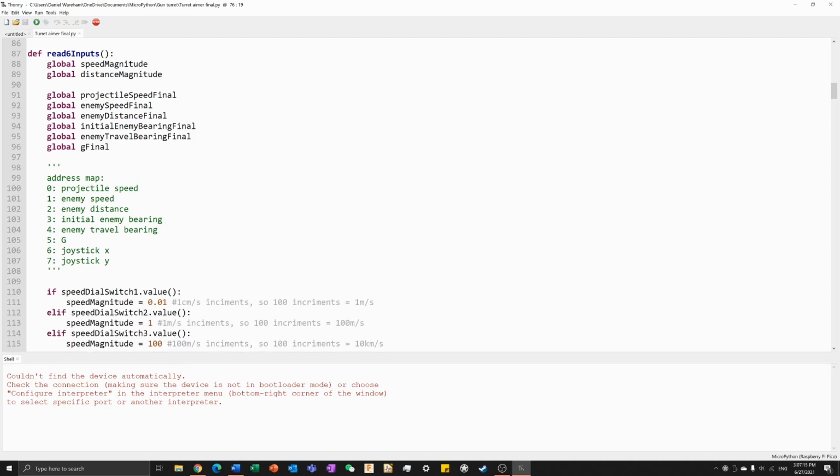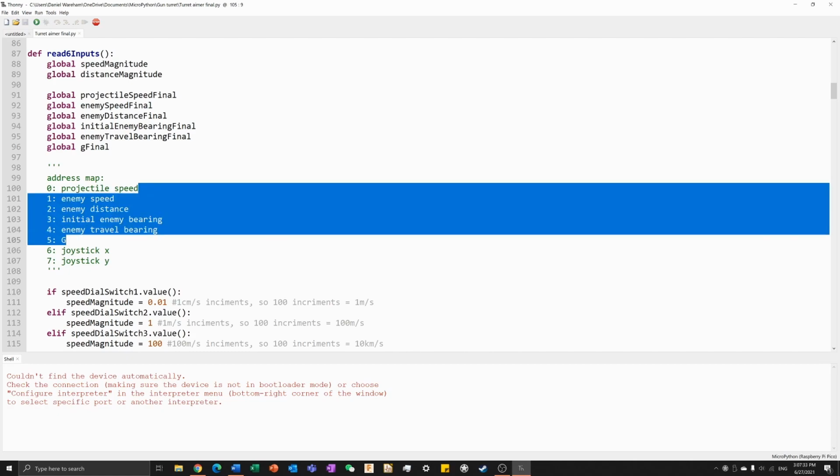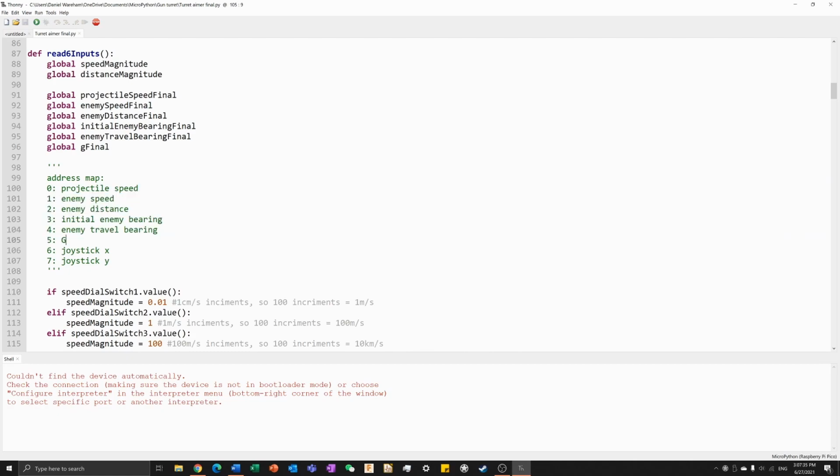So now these are the 8 analog input pins, well, not input pins, but inputs which can be read, numbered from 0 to 7. So that it can be addressed with just a 3-bit binary value. The first 6, labeled 0 to 5, are the ones required for automatic calculation, and the last 2 are the 2 axes of the joystick used in the manual calculation. So these 2 aren't actually accessed at all in this function. They're used in the manual section.